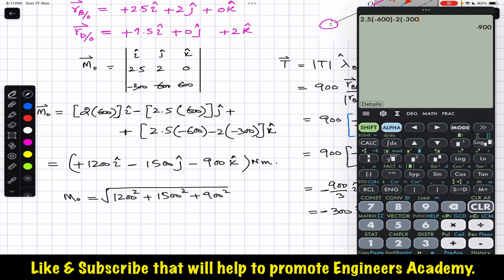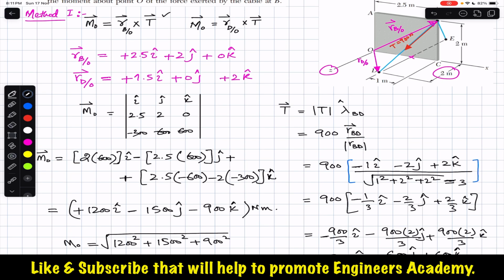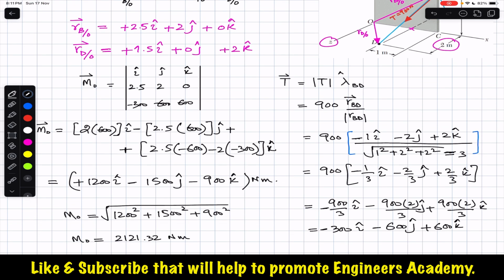So 1200 square plus 1500 square plus 900 square gives us the magnitude equal to 2121.32 Newton meter. So due to the 900 Newton tension at point B, acting from B to D, it produces a moment of magnitude 2121.32 Newton meter about point O.